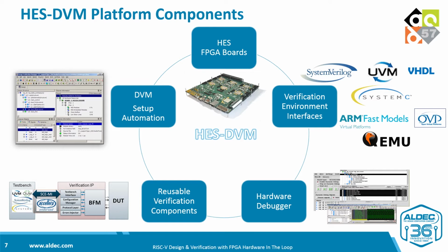Reusable verification components is a library of commonly used transactors and monitors like AMBA AXI, USB or PCI Express. And last but not least, the hardware debugger. It provides comprehensive debugging features and improves productivity while debugging corner cases detected during emulation.